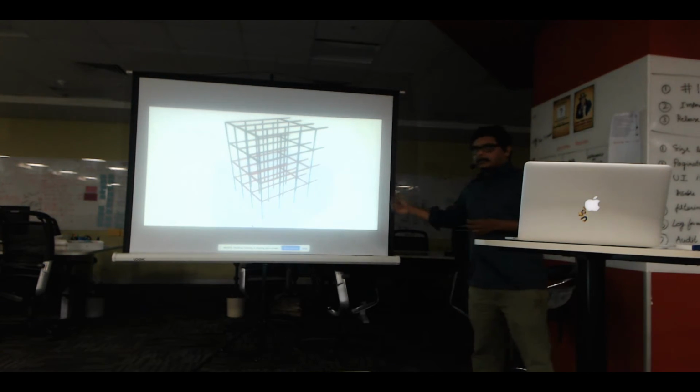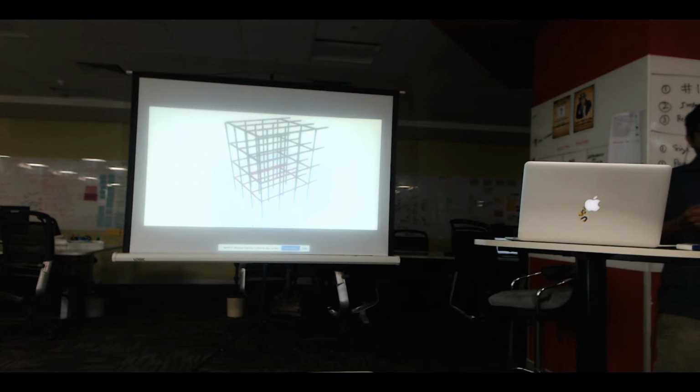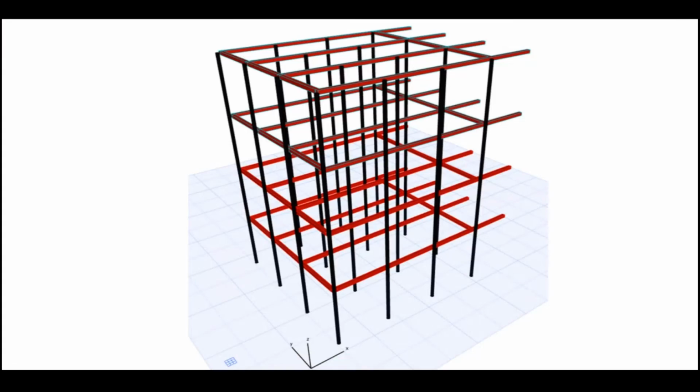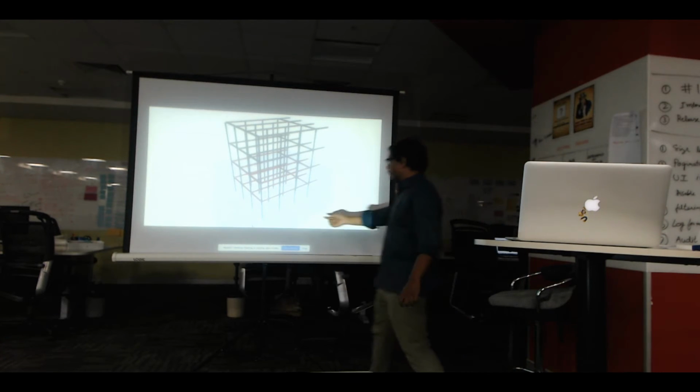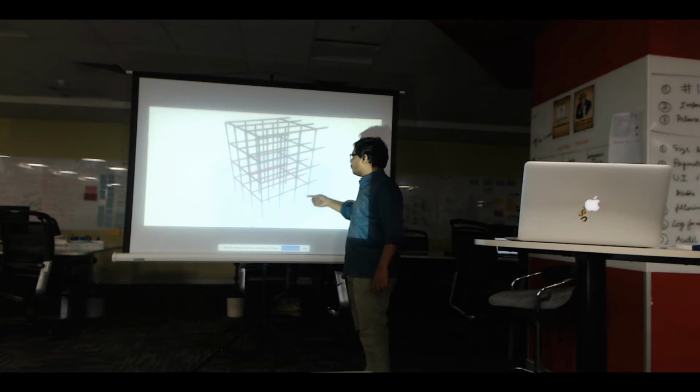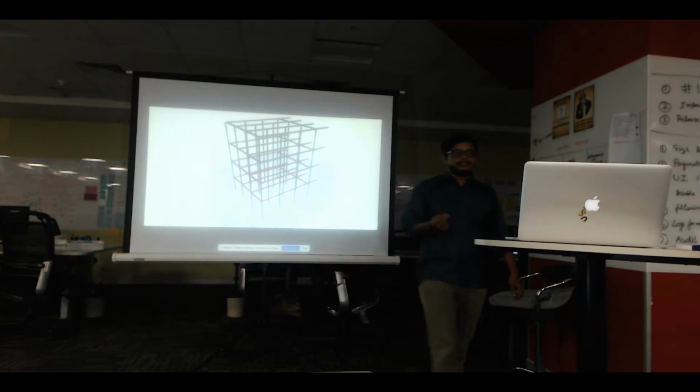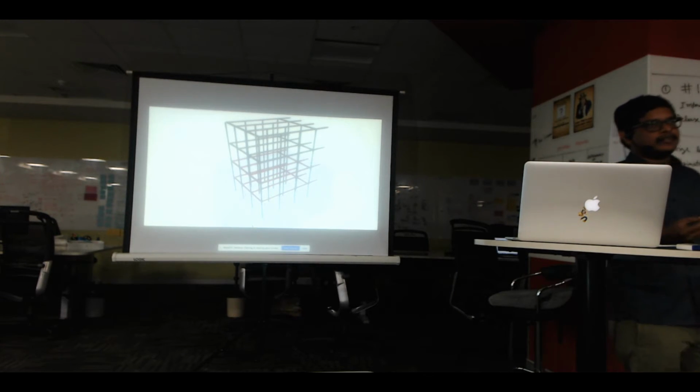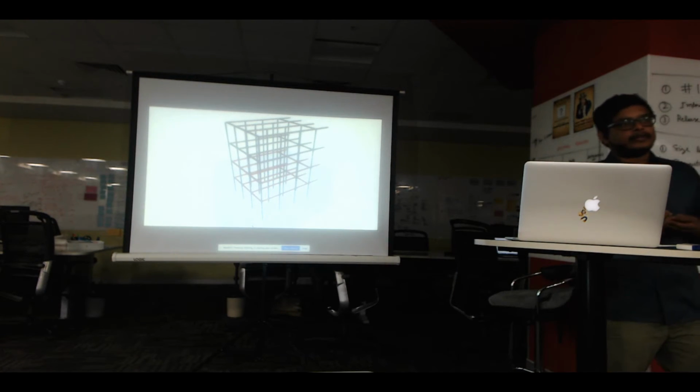And even with this solution, if it is an 8 cross 8 cross 8 LED cube, we have 64 columns, right? So we will need 64 plus 8 layers, so 72 pins. Again, we are short of the IO pins in the microcontroller.